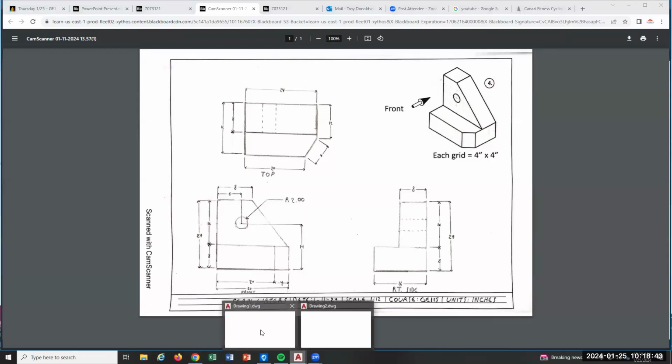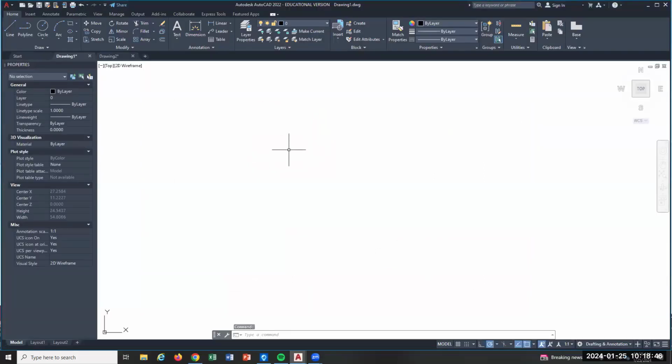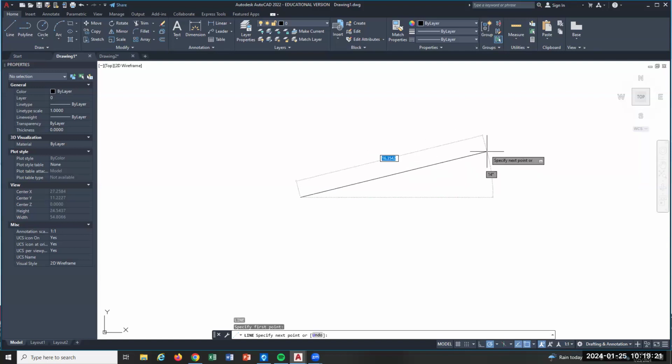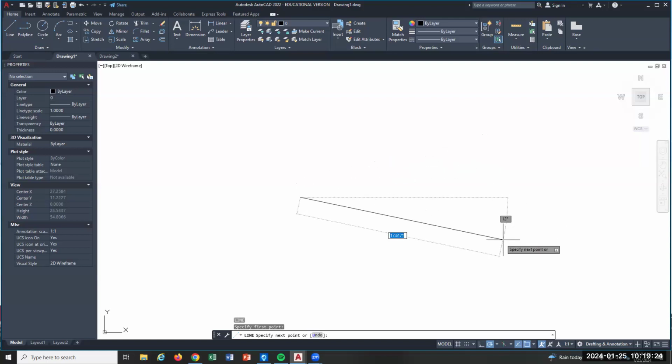All right. The easiest way to draw is what I call just point and shoot, just aim and shoot a line. So the line can start anywhere. When you pick the first spot, you get the rubber band attached to your starting location. So I'll do that again, line, enter. It says, specify the first point. It's trying to talk to you, right? That can be anywhere to begin with. So I just pick button. When you do that, anytime you do that, move the mouse so you can see what's going on, right? So there's the start point.